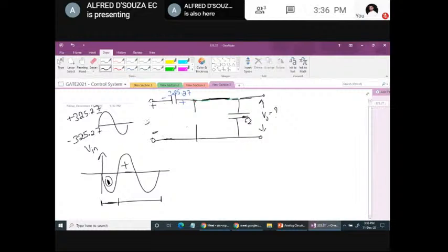And what is the peak voltage here? 325.27. And current will flow in this particular loop, charging capacitor C2. To what value will it charge? It will charge to the peak value, that is 325.27. From the previous negative half cycle, 325.27 volt is already there in the capacitor.